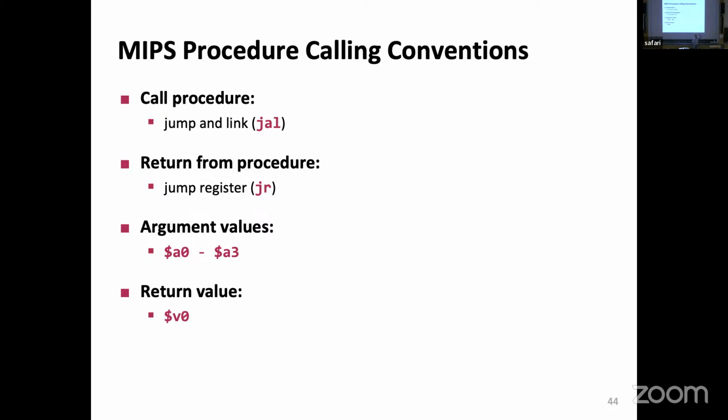Somewhere in memory, I was here, and if it wasn't the function call, I would land in the next instruction, and that one has an address. Jump and link is like a shortcut instruction that at once both jumps to the function and at the same time memorizes where it should return to, in a register that we call return address, or RA.